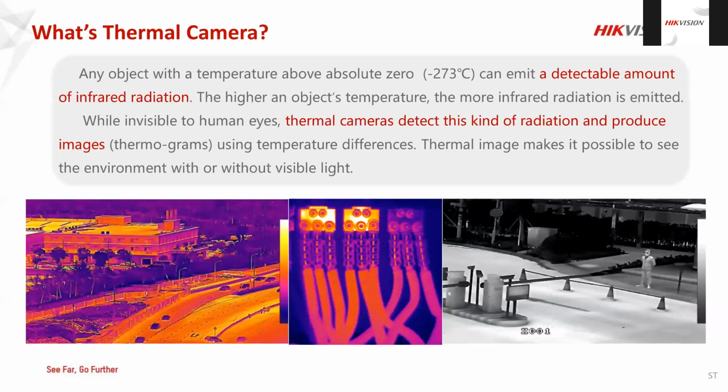So what we do is use this radiation to identify the temperature. The beauty of this is that it is not visible to human eyes. So we use some special kind of hardware to generate the thermography image, and especially this is achieved by understanding the difference in temperature of each point. If you are looking at a table with some objects on it, some objects might be hotter than the others. So the emitted infrared radiation will differ from place to place. So we can identify that and get an idea about the surface temperature at each point. That is the basic technology.